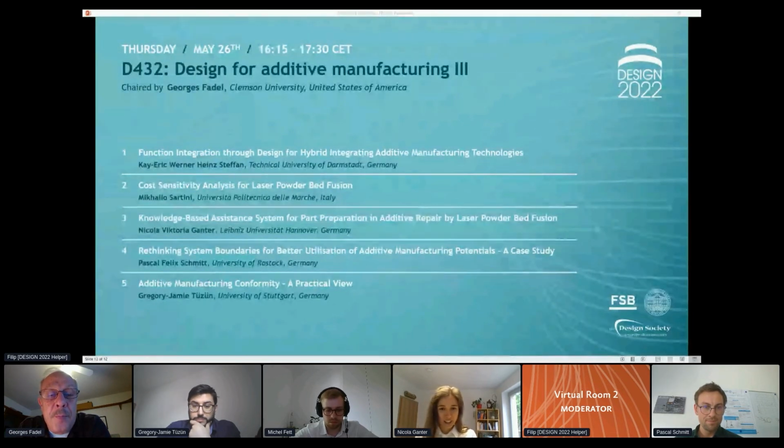Thank you. I think for the quality, there's only one difference, and this is that you always have a certain offset between the repair volume and the old part. So you need to consider that this offset should not be in an area where it is bad regarding the function of the part, and in an area where you can't post-process it. That might be in an area where you have internal channels or inner structures that you can't post-process.